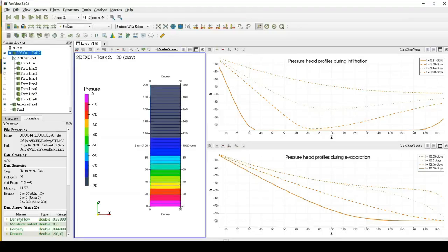Locate this example in the folder of Pipeline Browser, Tree View. This menu on one of the toolbars at the top of the window lists all variables from your simulation. Select any variable from the list to change the simulation variable result for visualization.